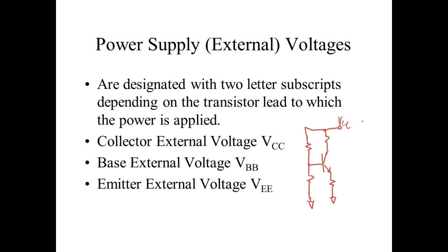In transistors, it could be any voltage. The voltage depends on the design, and we'll figure out how we can bias it. So normally, we're going to figure out how we can bias it with one battery, right? You understand? We don't want two completely different power sources to make the dang thing work. We can figure out how to use resistors to get voltages. So what can we get with resistors? We can cause voltage drops in resistors. So we'll figure out before long how we can bias all these things with one source.